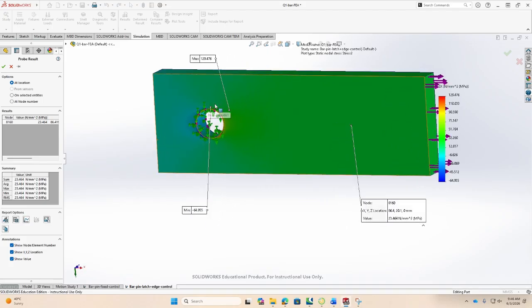Because in reality, like I said, you will have to consider a smaller area around it to simulate the effect of the washer and the bolt contact on the surfaces, because the force will be transferred through friction to the bar, isn't it? So in reality the stresses will be slightly lower, and you can do that. You can go back and create a small circle here, and that will allow you to select that surface in the software and apply the load there as well, but that will just take me more time. My class time is now almost finished.